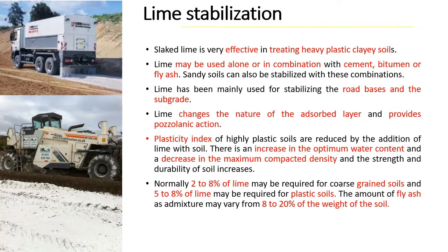There is an increase in the optimum water content and a decrease in the maximum compacted density, and the strength and durability of the soil increase. Lime soil stabilized mix is used to construct subbase and base course for pavement.